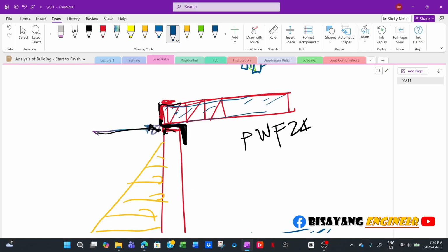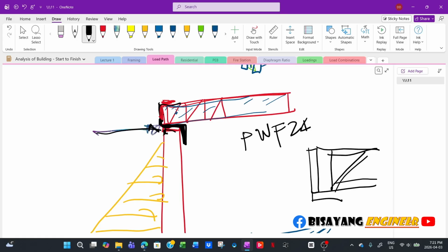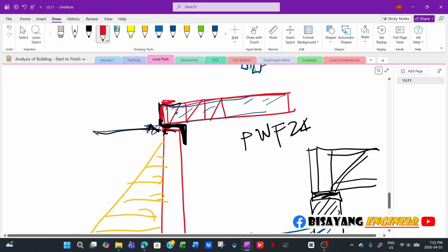surface, to transfer that load to the foundation, if this is your rim board, this is your trusses, right? This is your trusses like that, and then this is your sill plate, and then your ICF, this concrete core. Now, to transfer that horizontal load, you either design the rim board to resist all the lateral load, because the sheeting is right here and you have nailing from your diaphragm design, so it transfers to the sill plate, and the sill plate to the concrete core.